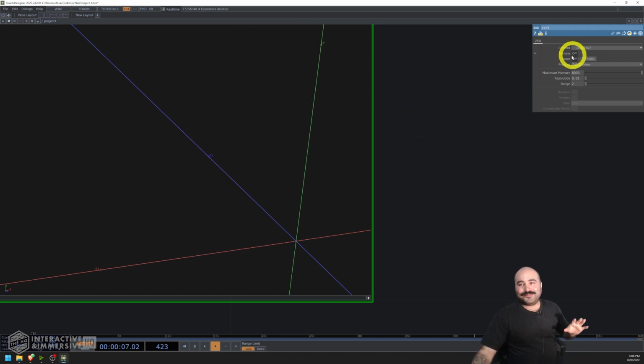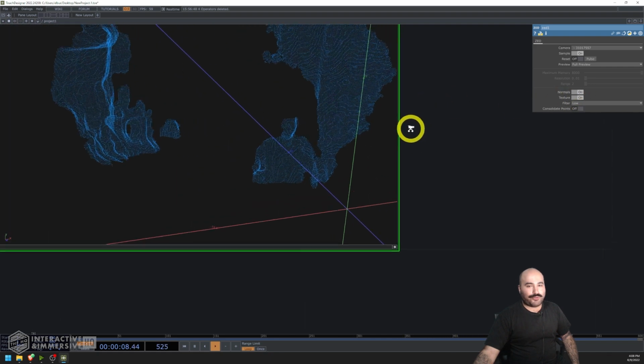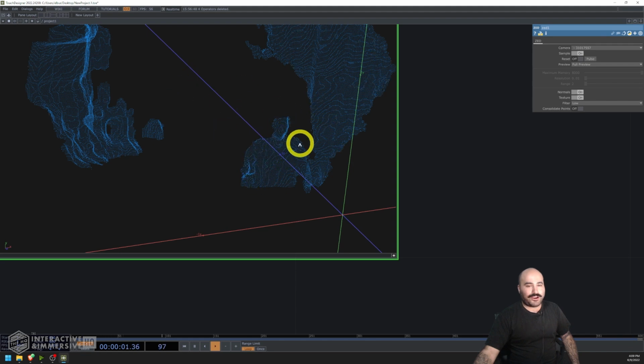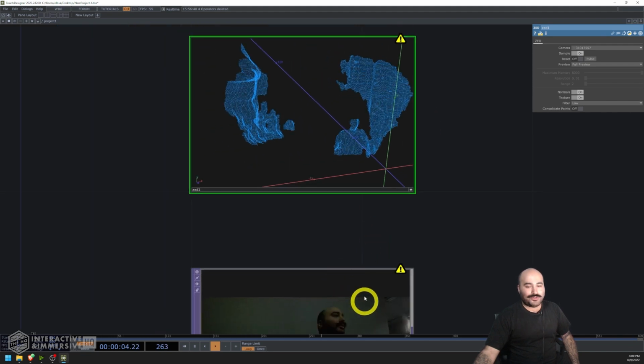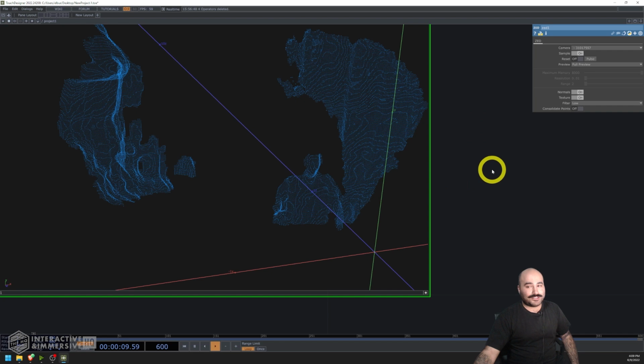So I'm going to go ahead and reset that. I'm going to hit sample again. And this time, once I turn the sample button on, I can see that these parameters at the bottom are now enabled. I actually want to go ahead and turn on the normals, which is going to compute normals for the geometry that it creates after. And I'm going to turn on the texture button. Once you turn that on, the Z SDK is automatically, periodically through the scan, going to take pictures of the environment through one of the cameras and then keep those sampled inside of that Z top that we created in the correct UV position, which we're going to see is really, really cool. Now, we'll come back to this filter in a moment. Let's go ahead and turn off our sample.